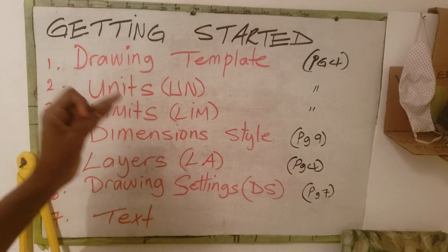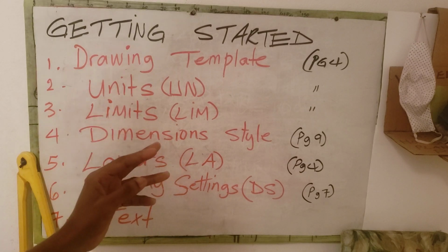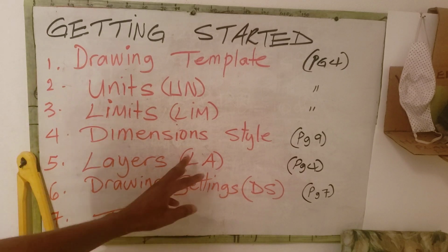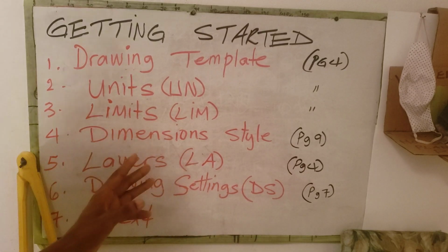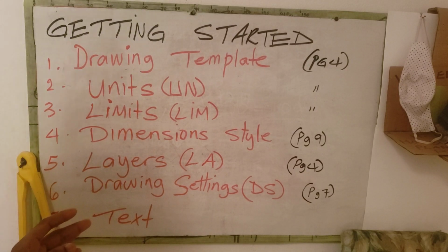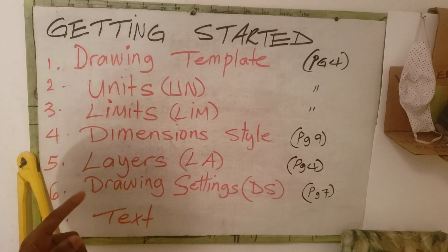You need to change the color of the layer. You'd also need to change from default to whatever line weight thickness you want. In this case, you're going to use 0.25 for most lines. For outline, you need to choose between 0.3 to 0.7.